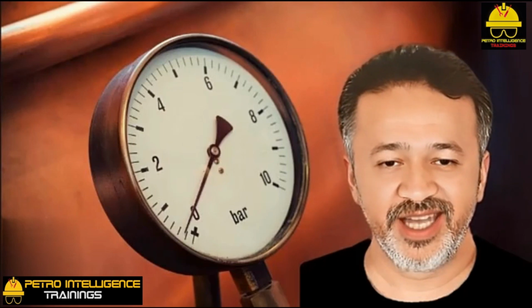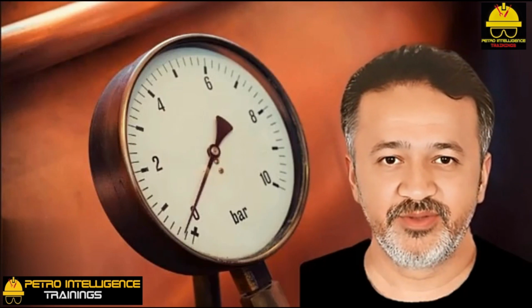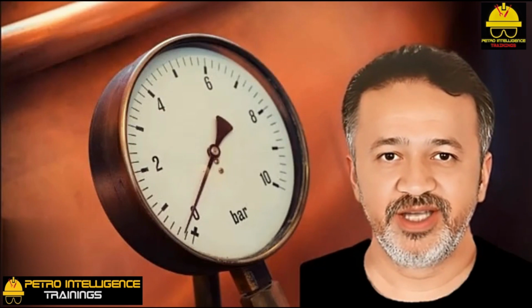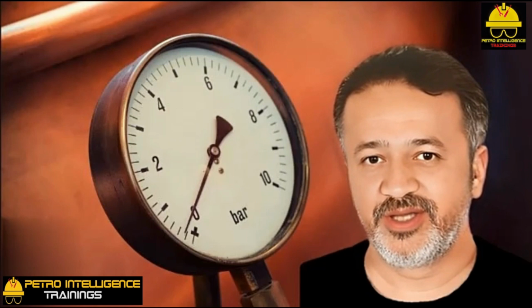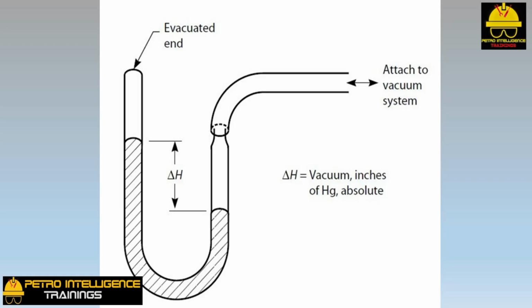A vacuum pressure gauge reading 25 inches Hg in Denver would correspond to an excellent vacuum of 1 inch Hg absolute pressure, 26 inches Hg minus 25 inches Hg. All these complications can be avoided when making field measurements by using the vacuum manometer shown in the picture. The difference between the two mercury levels is the correct inches of mercury absolute pressure, or millimeters of mercury, mmHg. A drop of water on the evacuated end of the manometer will result in a falsely low vacuum reading.